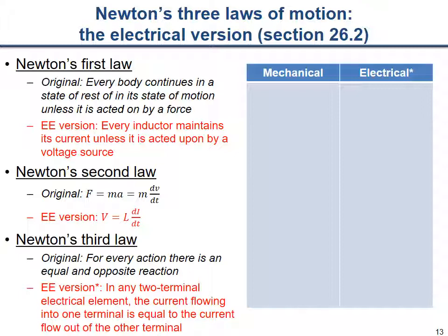It turns out there are duals of all of these, but let's complete this analogy by making analogies from various components of the mechanical model. Force we can essentially replace by voltage. The voltage will force current to flow through the circuit, for example. Velocity in the mechanical model is very well represented by current in the electrical model.